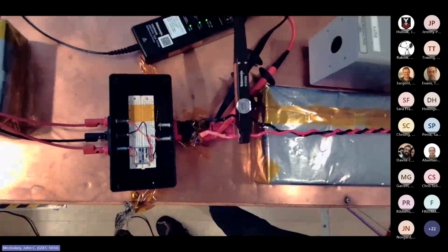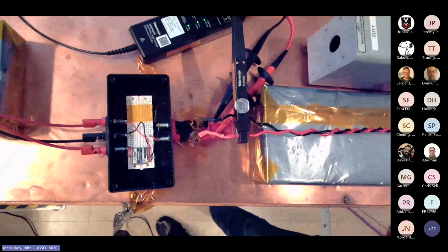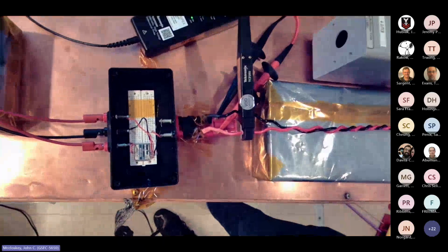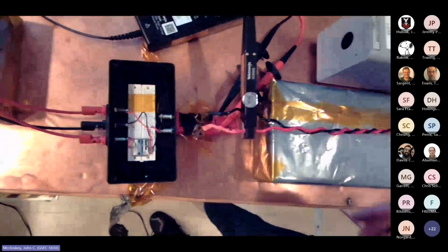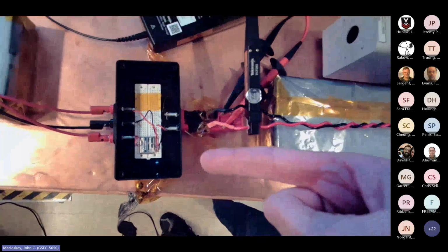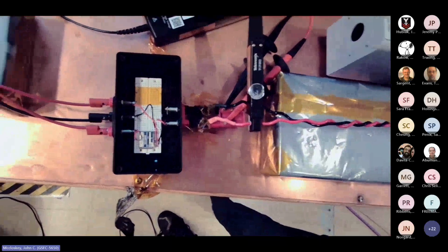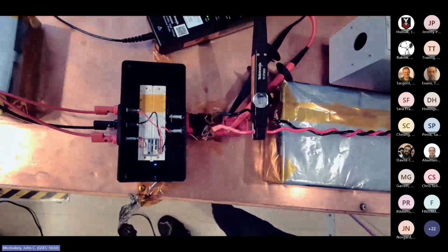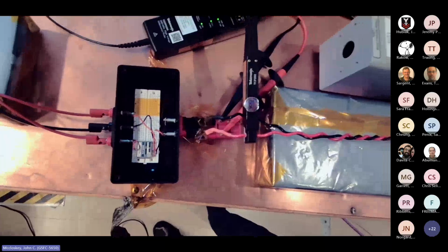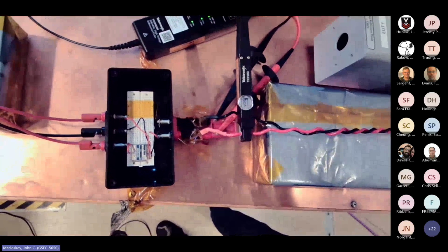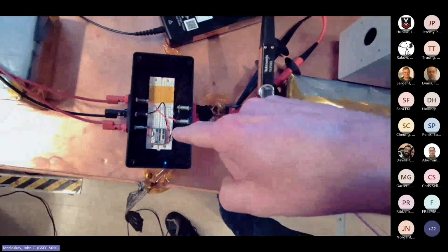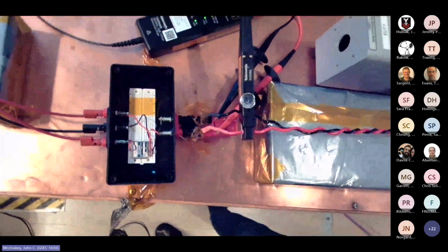And to make these things work properly in a system, you want to very significantly filter the input and the output. Clearly, I haven't done that here. I intentionally wanted a noise-making thing. I always say for EMC engineers, the world is conceptually rather simple because we have two columns. There is one column for noise-making things, a second column for things that may be sensitive to those noise-making things. So this is a noise-making thing. That's exactly what I wanted for these demonstrations.